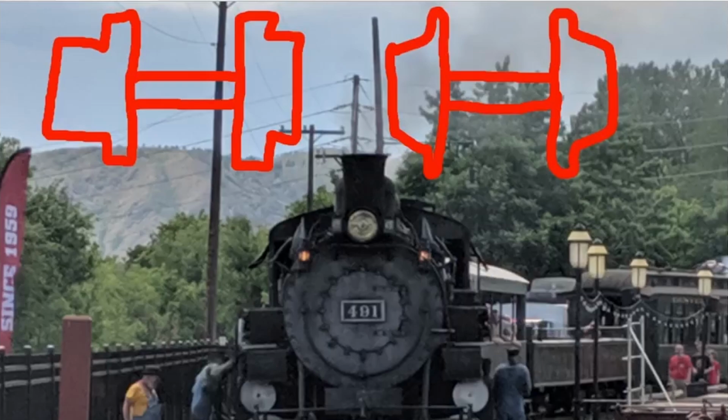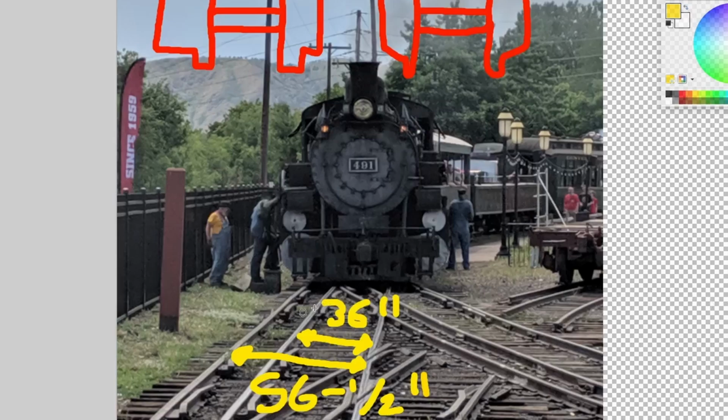That just makes sense. So this is a good example picture of 3-rail dual gauge, where we have one common rail shared by both, then the 3-foot narrow gauge rail, and then the standard gauge rail over here. So both trains run on this outside rail, have one wheel on that, but narrow gauge trains use this rail, standard gauge trains use this rail.